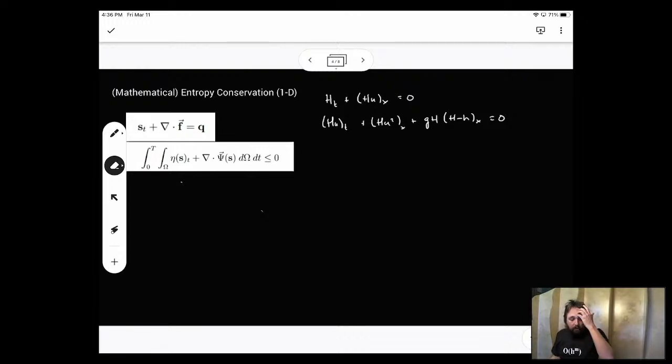Okay, so the advective form, essentially what we can do starting from this conservative form here is apply volume conservation and rewrite this whole statement as h multiplied by du dt, this is the velocity, plus h u du dx plus gh dh dx, with big H minus little h, so the free surface height, being 0.